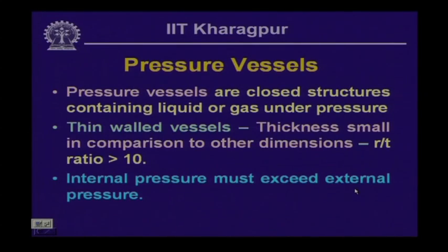Now, let us look into the aspects which we are going to deal with today. As I have told you, pressure vessels are the containers in which gas or liquid is put under pressurized condition, and thereby it exerts pressure on the internal surface of the container. If that internal pressure is higher than the external pressure, the body will be experiencing stresses, and basically there will be tensile stress in the body. Our objective here is to evaluate those stresses in such pressurized containers. It has quite wide applications in industry, wherein we use compressed air, or even water flowing through a thin walled pipe, which are also examples of this kind of pressure vessel.